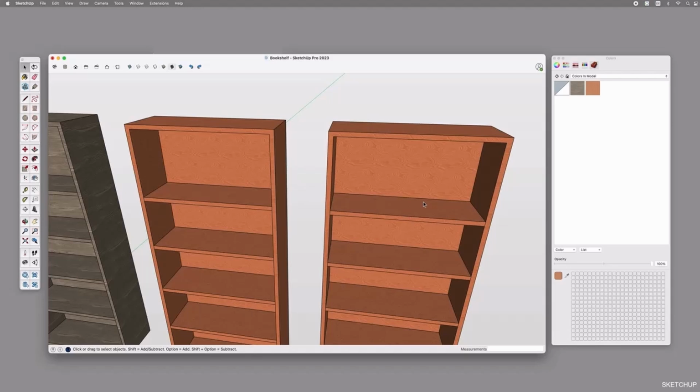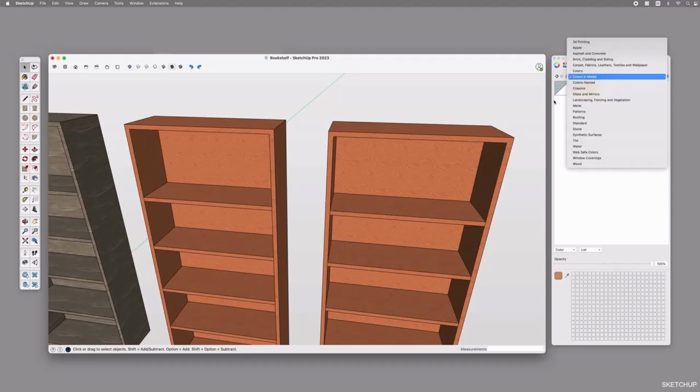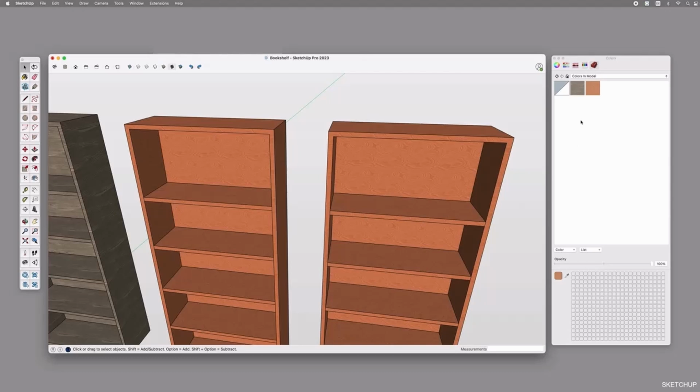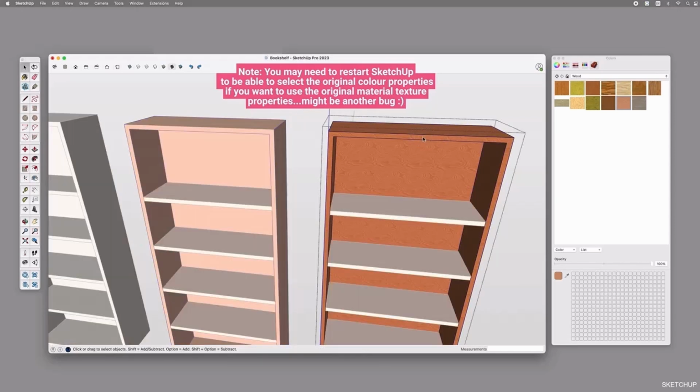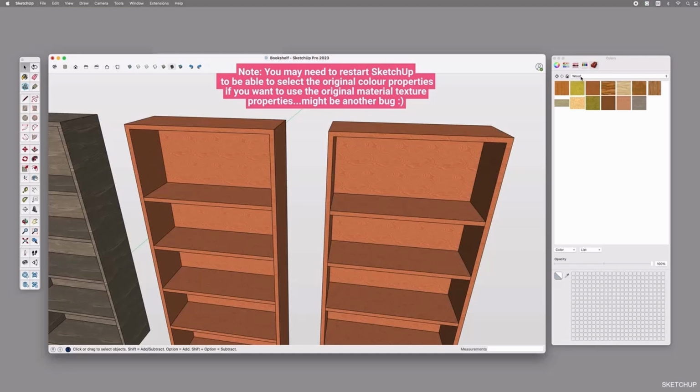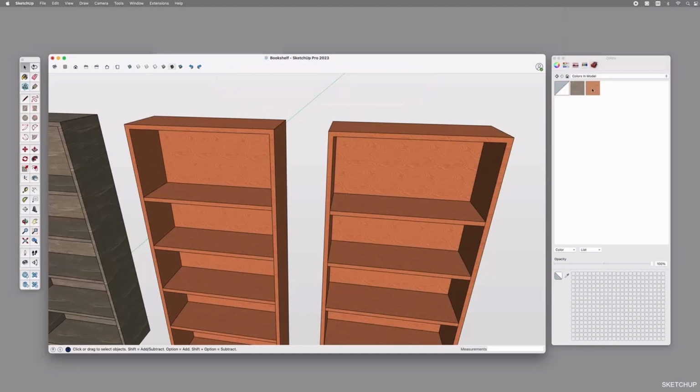What is essential to note here is that when you modify the properties of a texture within this specific model, it only applies to that particular instance. If you revert to the built-in materials from SketchUp and reselect the same material we have chosen at the beginning, you will find that it retains its original properties. This approach allows you to have a backup of the main texture, and it's advisable to primarily change the texture under the In Model section to avoid altering the original textures.